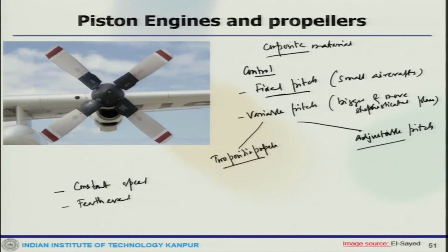Then we could have feathered. So, again, turning the propeller blades so that they are edge on, making a very shallow angle to the oncoming air, minimizing the air resistance and allowing the plane either to keep on flying on its remaining engine or glide to a crash landing.